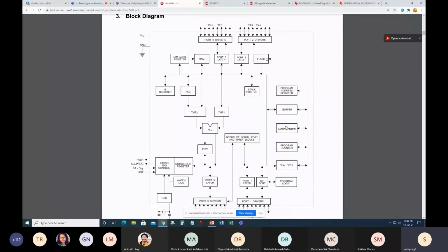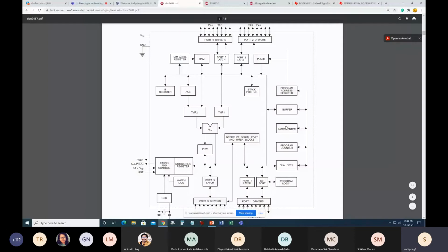I explained yesterday the name FN tunneling, Fowler-Nordheim tunneling, which you will possibly study in VLSI engineering. That's the physics behind the special transistors that store a certain charge, and if the charge stays stored even after power off, you are making the transistor a memory transistor.